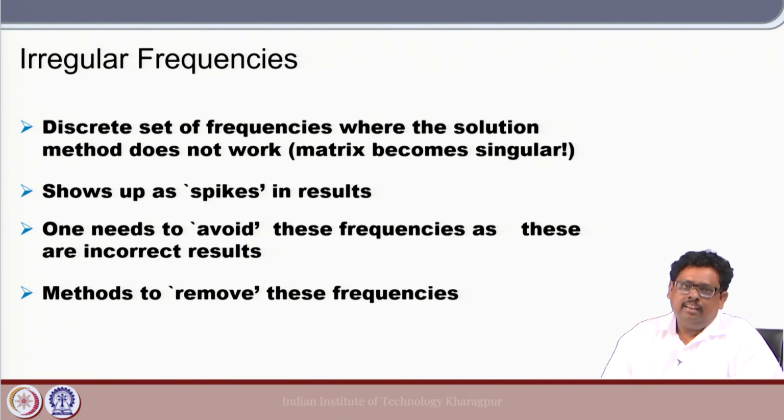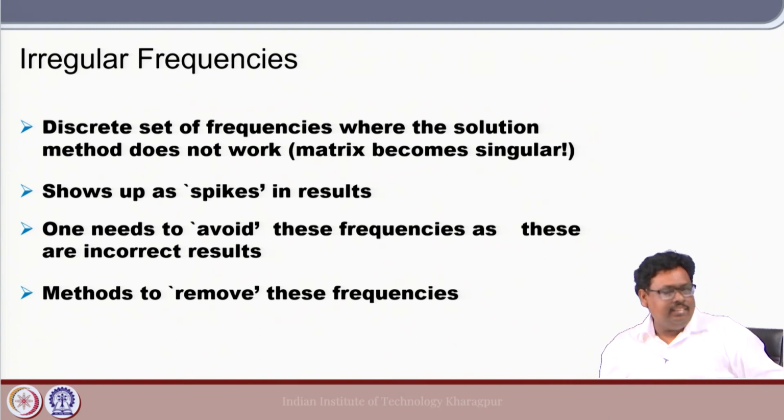Sometimes, when you are evaluating the RAOs, we can have a sudden spike or peak, and if we really do not have some knowledge about why this spike may come, we tend to defend our result and say that in this frequency that is what is going to happen, right? And then you are defending a wrong result, blindly trusting your software. So, let us see what I mean.